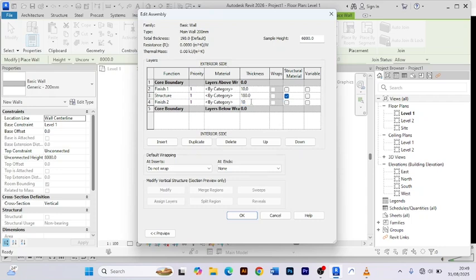10 millimeter constitutes plaster and paint. And then the 180 is basically the main brick structure. The brick structure that has no plaster and the paint. That is the structure inside. So now we have assigned thickness. We can come to material. You just click around here. You see these three dots. It will open. Let's wait for it to open.